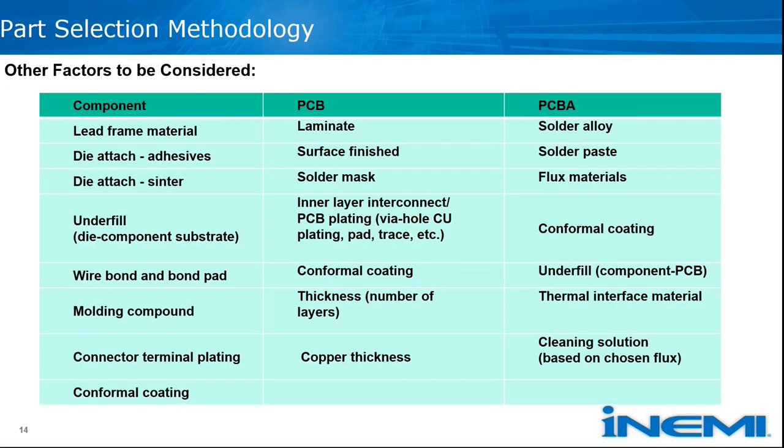Part of what we'll have to do also, as we do the board level testing, we'll have to design the PCB because it can play a critical role in the reliability. And the team will need to finalize and agree upon the design. Modeling and simulation will be important to help predict the potential effects of the PCB on the component reliability. So this chart lists many of the different variables that we will have to consider from the component, the PCB, and the assembly.